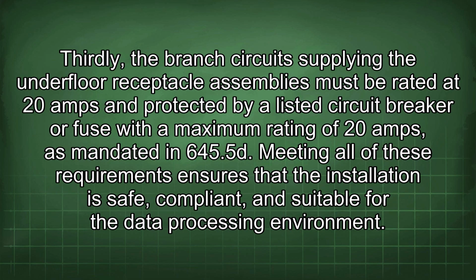645.5. Thirdly, the branch circuits supplying the underfloor receptacle assemblies must be rated at 20 amps and protected by a listed circuit breaker or fuse with a maximum rating of 20 amps, as mandated in 645.5. Meeting all of these requirements ensures that the installation is safe, compliant, and suitable for the data processing environment.